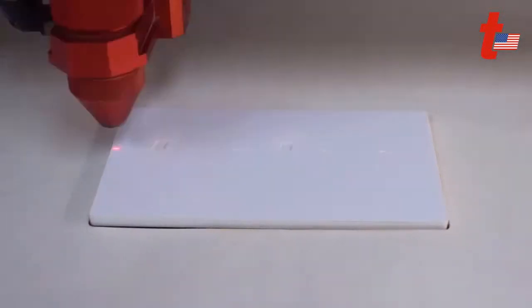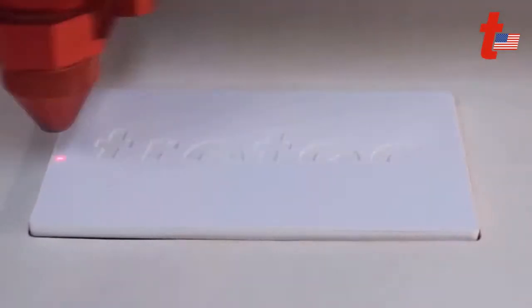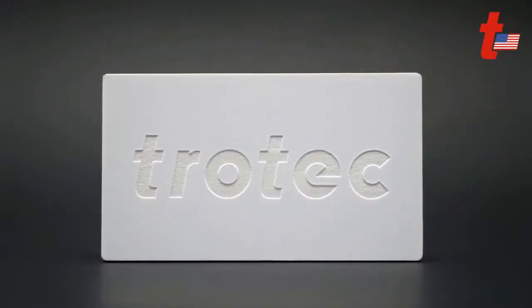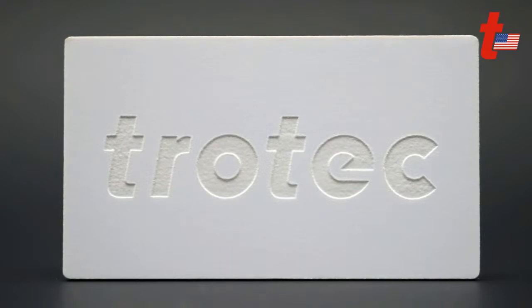So here's what it looks like to engrave. You can see it does produce a shadowy effect. We get a nice subsurface embossed look, almost a watermark look. It is recognizable, it is readable, but it is not the greatest. The edges are a little bit rough. You can see the melty look I was talking about right out of the laser. The edges are not as sharp as some materials like acrylics, but again, it is a recognizable mark. It is a subsurface mark so that it can't be easily removed. So if you're just putting something like a part number, it is going to be a readable part number throughout the life of the actual product, because it is marked subsurface into the plastic itself.